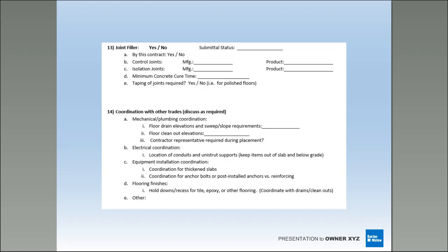We're getting an aggregate polish. With an aggregate polish, I'm going to cut that surface down just enough where now that cleanout's high. These are things you've got to talk about when you're in there. Am I doing an aggregate polish, a cream polish, a sand polish? How deep is my cut? Again, all needs to be coordinated with all trades to make sure we have that success at the end of the project. The last thing you want to get into is finger pointing, because once you go there, everything falls apart. So if you're going to finger point, this is your time to finger point during this conference, okay?